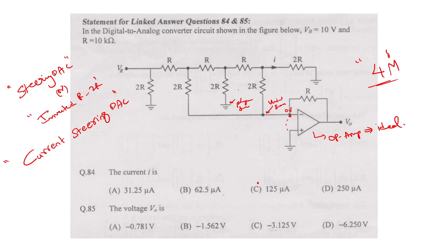So either you connect the resistor to physical ground or connect it to the virtual ground. If you connect to the virtual ground, you are pumping the current towards this node. This current sums up, and then the other current will come here. Since the input current is zero, whatever current is coming in has to flow to the output node. This is very wonderful actually.